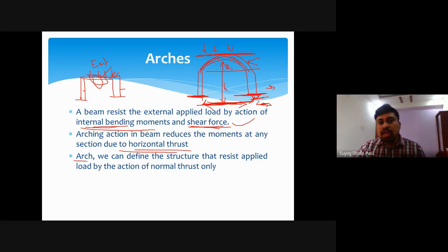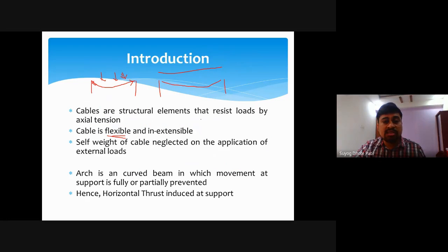Again, if it is a conversion of a cable, this is under compression because the vertical or gravity load is coming from the top over this arch, and it will try to push the arch in the downward direction. So the whole arch will be under compression. That's why, in the first slide, cables are the structural members which resist the loads by axial tension, because of the nature of this cable.